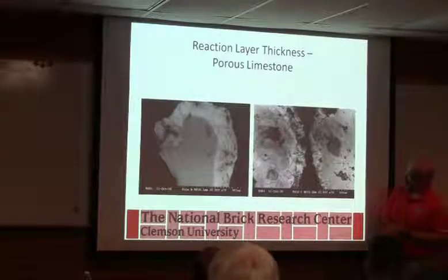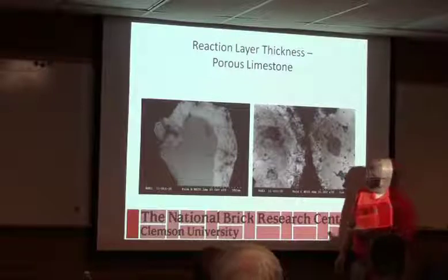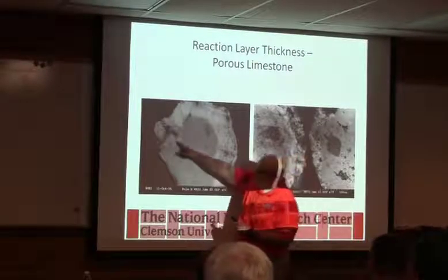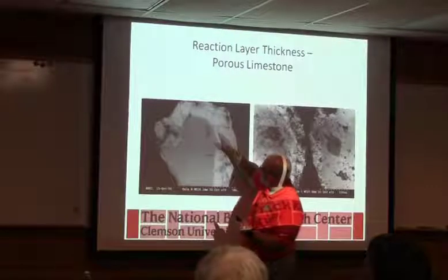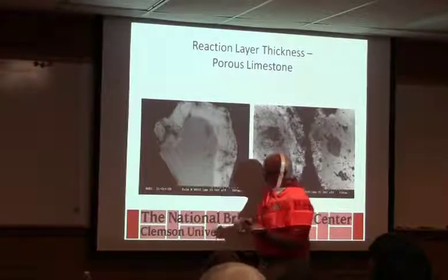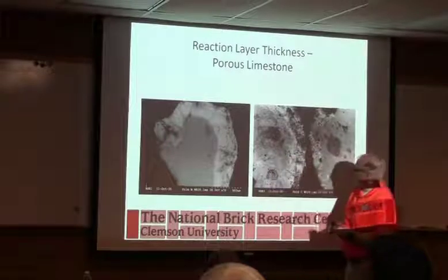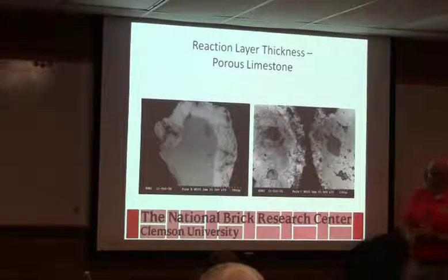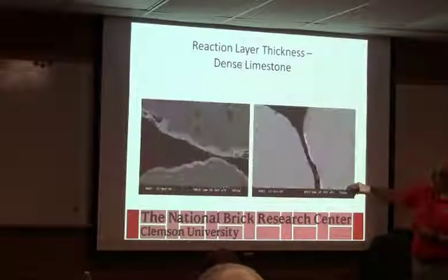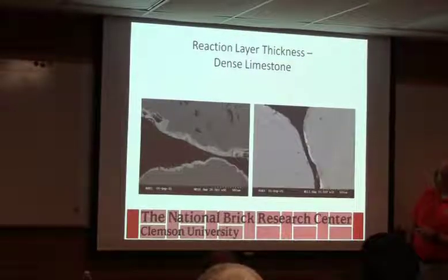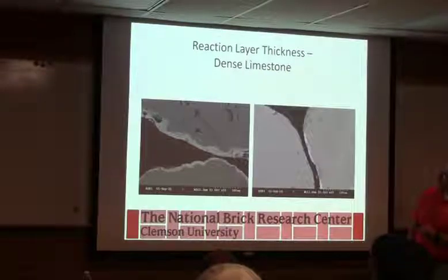This is one of the real porous limestones. One of the things I always think is interesting is you notice how that layer is thicker wherever there are usually some cracks or some voids. The gas seems to follow those, and you get more reaction. So that's the difference. That's a porous one, and that's a real dense one. You just don't get as much reaction.